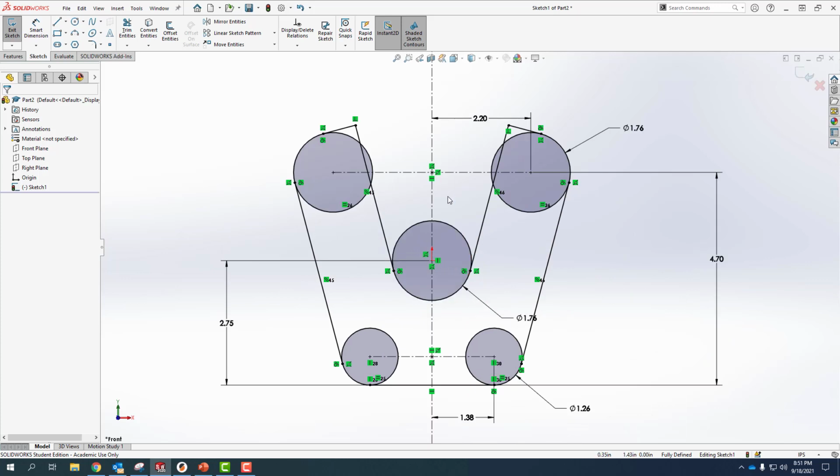And you say, well, I want to trim things out so I can get the sketch to look like what it is in the drawing, but we don't need to, because the drawing says that we should extrude this to be 0.25 inches thick, and we have all the geometry we need. Now, is it wrong to trim out the geometry? Absolutely not, but it's unnecessary.